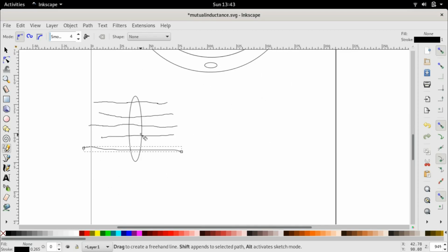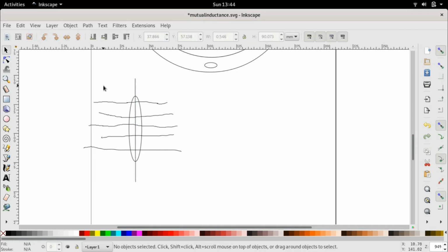this rotor coil is aligned in such a manner vertically, right? Vertically along this axis. So if I can draw a certain axis, let me just draw this vertical axis and say that this is my vertical axis and this coil is along this vertical axis, as it is quite obvious, in such a case, the linkage of the stator flux with the rotor is extremely high.